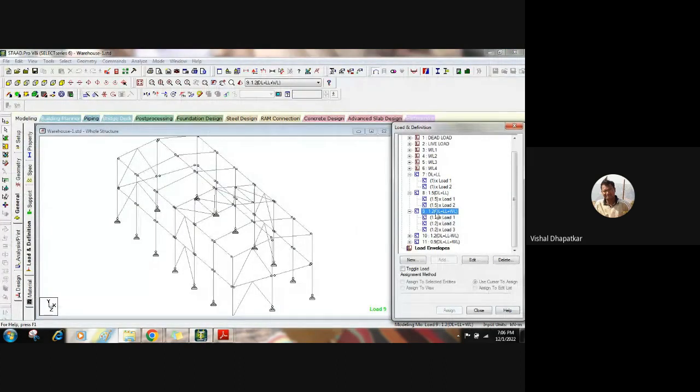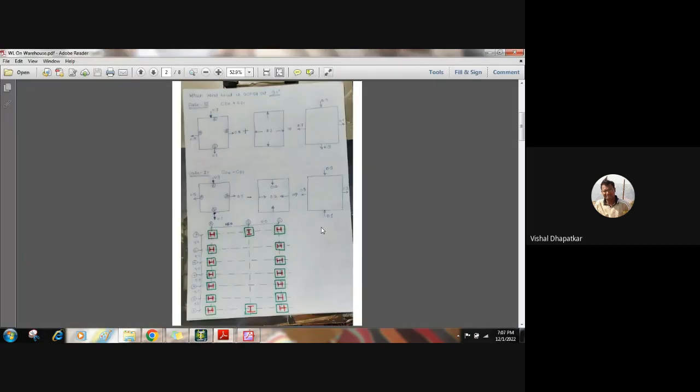So this is when wind load is considered. The factor for dead load and live load will be 1.2. Similarly, this is wind in the plus direction, wind in the minus direction, or we can say wind is acting in the windward direction, and if we are considering minus, it means we are changing the leeward and windward direction. So 0.9 dead load plus wind load. This load case is considered to calculate the uplift force or tension in the support reactions, so that we can calculate the number of bolts required for the tension.